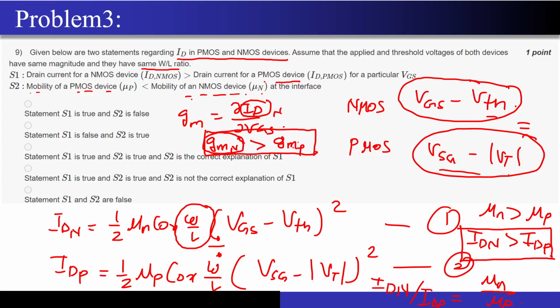It is not that there are no circuits with the PMOS transistor, but they are designed for different specifications. There are a lot of specs that you have to meet, right? There is linearity, there is noise, right? But if you just focus on the gain term, then we generally design most of the circuits using the NMOS transistors. If you open any circuits book, you will find a lot of NMOS amplifiers compared to PMOS amplifiers, and this is one of the reasons. That's why I took this example.